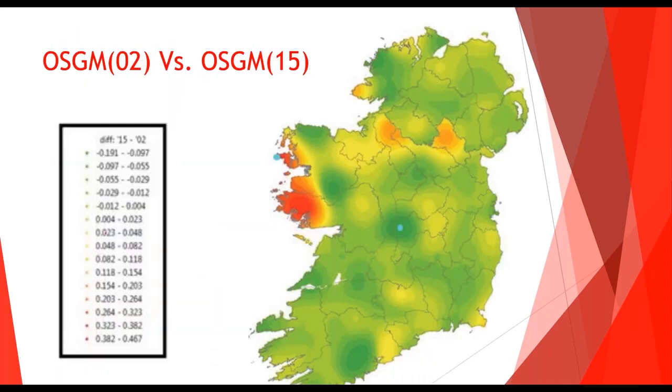Okay, so moving on then, why did we move from ITM to ITM 15? Because the grid is the exact same. However, the difference is the geoid. So if you're using a GPS and you change your coordinate reference system to ITM versus ITM 15, standing in the same location, we would expect to get the same position, within obviously GPS accuracies, within 15 to 20 mil in position.